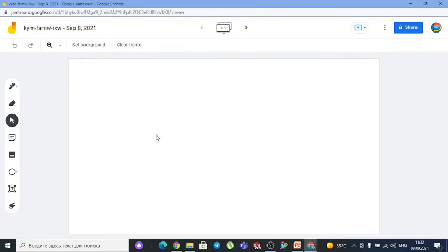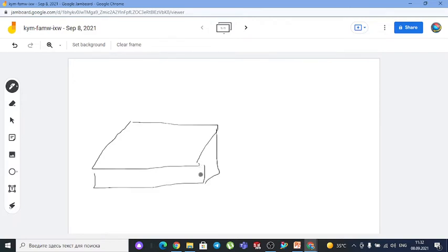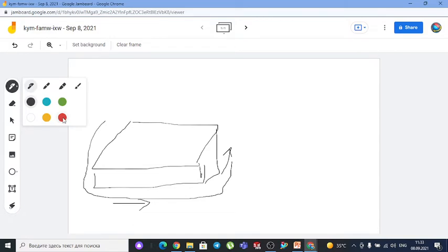Yesterday we have seen the milling operation. Let's analyze the difference between the milling and the turning operation. Yesterday we analyzed milling with a prismatic workpiece. The prismatic workpiece is fixed on the table, and the table can move horizontally and in the transverse direction toward the column. And we have the tool, in this case let's assume a face milling cutter.